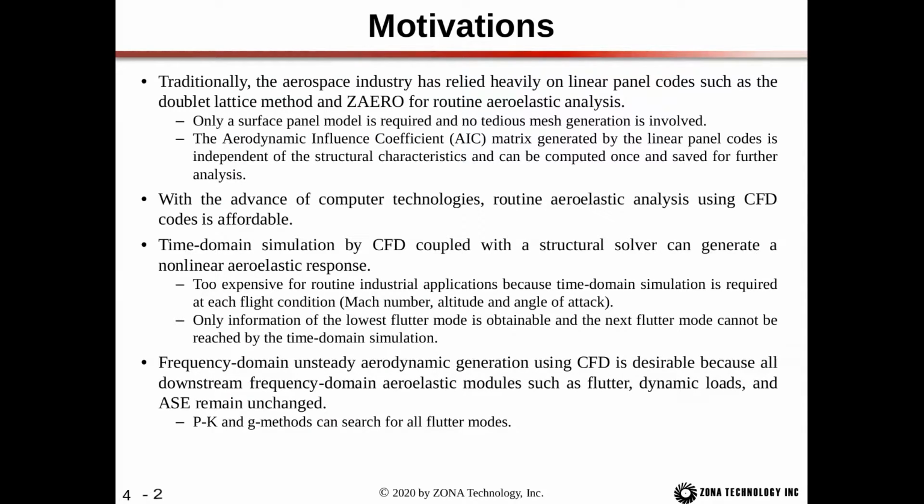Now, with the advance of computer technologies, routine aeroelastic analysis using CFD codes is becoming affordable. And the time domain simulation by CFD, coupled with a structural solver, can generate a nonlinear aeroelastic response. However, this is too expensive for routine industrial applications because the time domain simulation is required at each flight condition, which is Mach number, altitude, and angle of attack, where altitude, of course, represents the dynamic pressure.